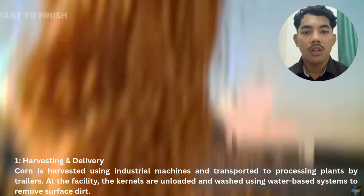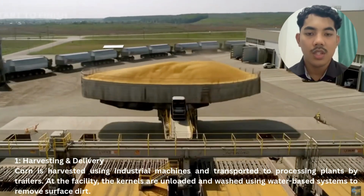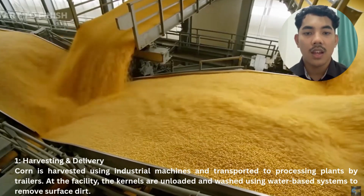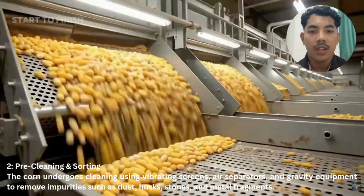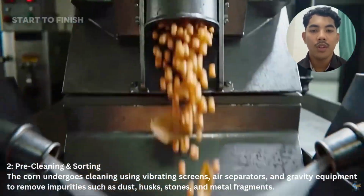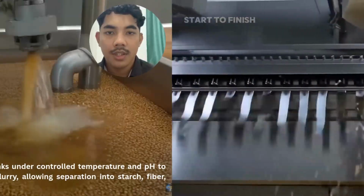Flow processing of the corn oil. Step 1. Harvesting and delivery. Corn is harvested using industrial machines and transported to processing plants by trailers. At the facility, the kernels are unloaded and washed using a water-based system to remove the surface dirt. Step 2. Pre-cleaning and sorting. The corn undergoes cleaning using vibrating screens, air separators, and gravity equipment to remove impurities such as dust, husk, stones, and metal fragments.